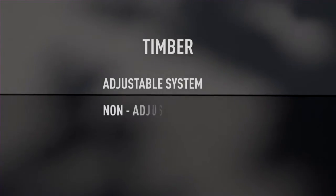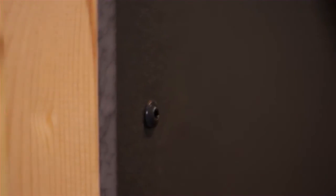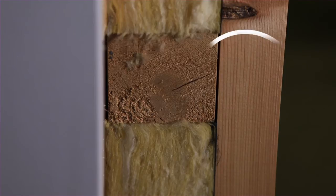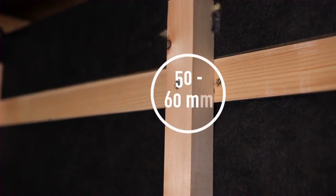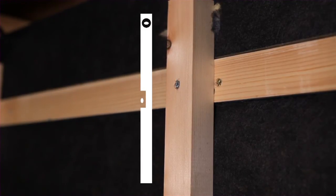There are three options for timber subconstruction: adjustable, non-adjustable, and the distance screw method. The grade of timber suitable for use in a ventilated facade and whether it is to be treated with preservative can differ from country to country. The batten should be a minimum of 30mm thick. Battens used behind the vertical panel joints or at corners should be 90 to 100mm wide, with the other battens 50 to 60mm wide. Ideally, the batten should be smooth on the front face and one edge to ease levelling.